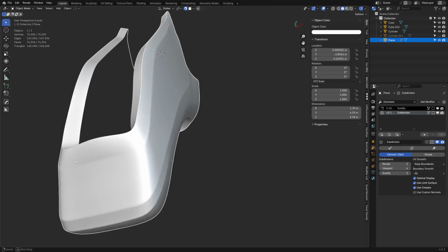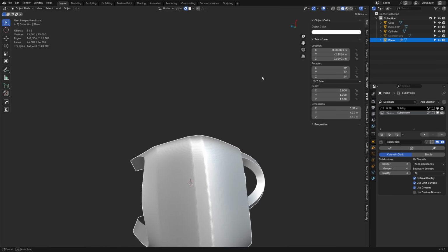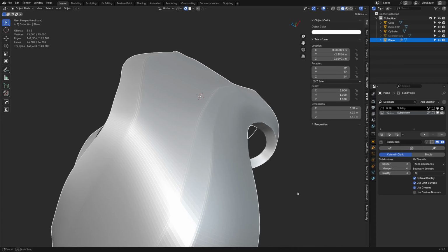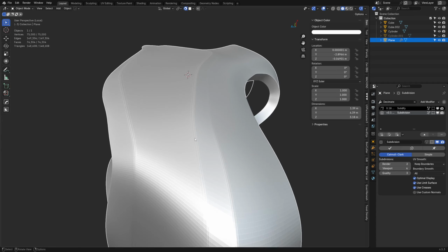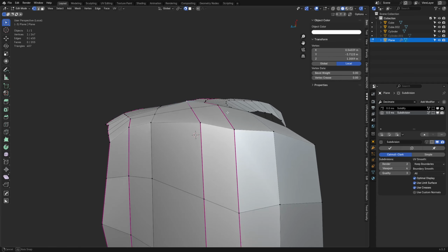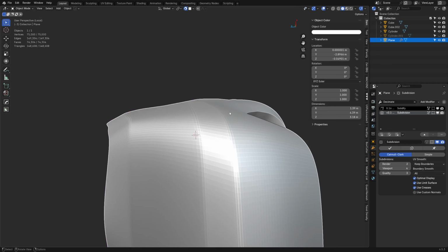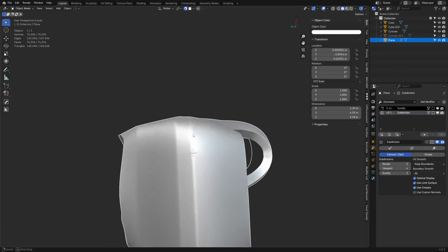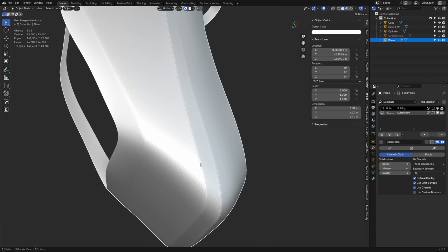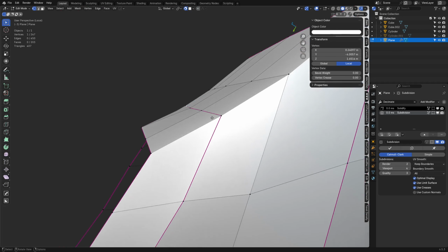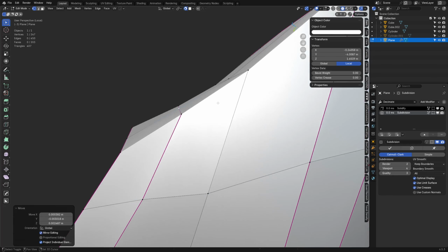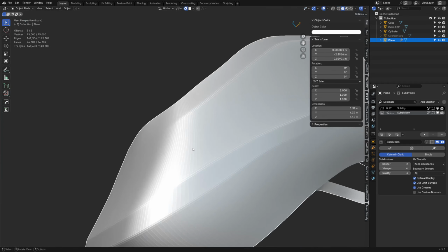This is one of the main reasons I like being able to spin the view. I can look at this model from any direction now and line up to it and say, is this flat enough, right? If that's not flat enough, I might take this edge and just pull it in a little bit. Maybe this one goes, then we get something more. This is really good for surfacing as well when you're working on subdivision mesh. Most people don't realize that. Definitely something you want to consider doing because it just gives you a better way of looking at it. And you get used to it after a while anyways.